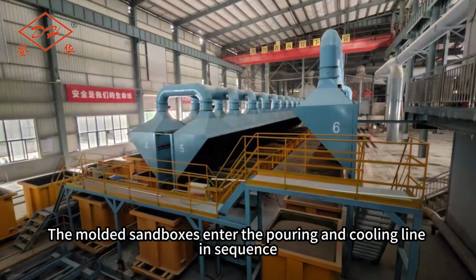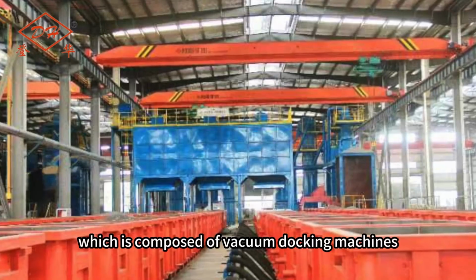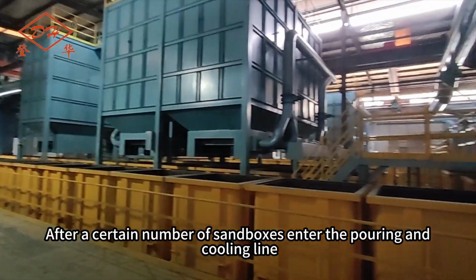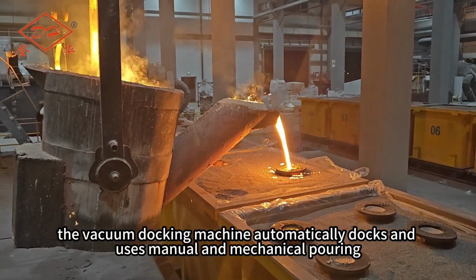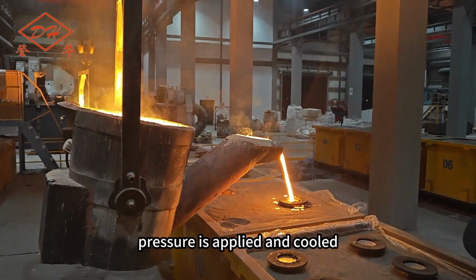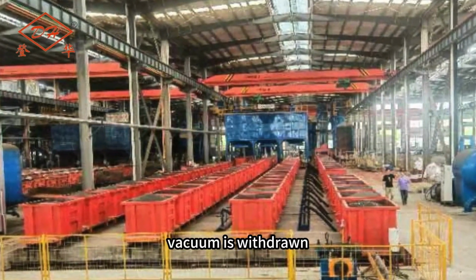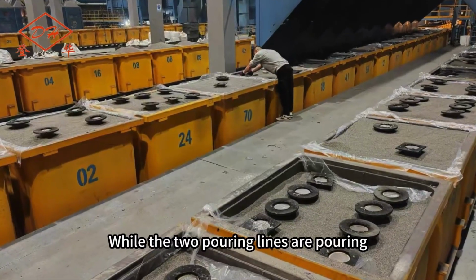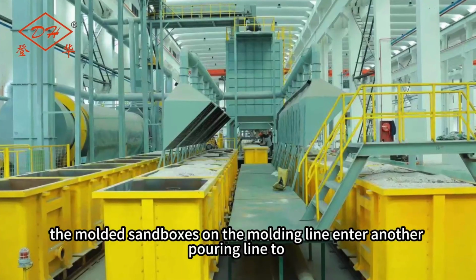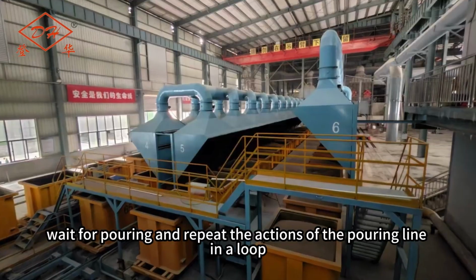The molded sandboxes enter the pouring and cooling line in sequence, which is composed of vacuum docking machines. After a certain number of sandboxes enter the pouring and cooling line, the vacuum docking machine automatically docks and uses manual and mechanical pouring. After pouring, pressure is applied and cooled, and then the vacuum docking machine is reset, vacuum is withdrawn, and cooling is carried out. While the 2 pouring lines are pouring, the molded sandboxes on the molding line enter another pouring line to wait for pouring and repeat the actions of the pouring line in a loop.